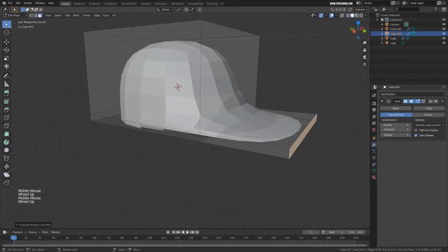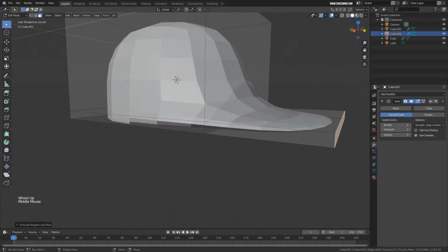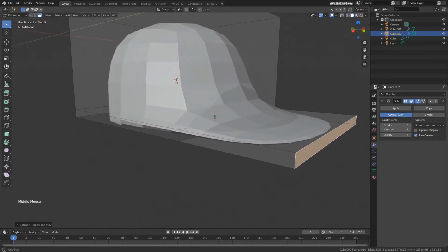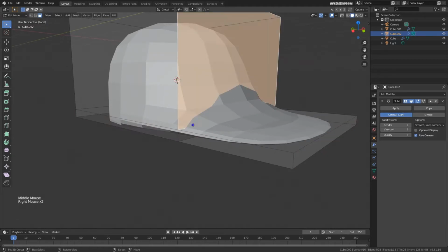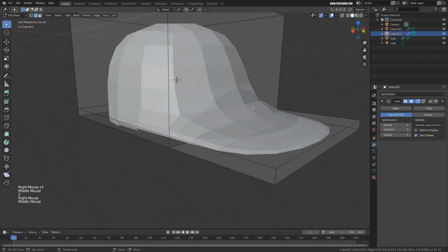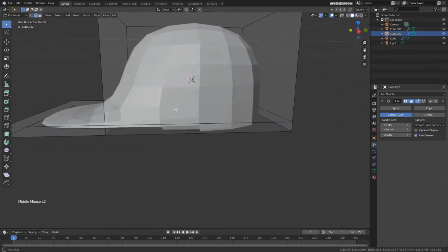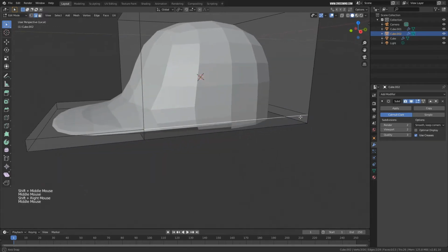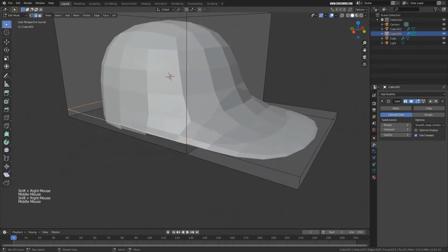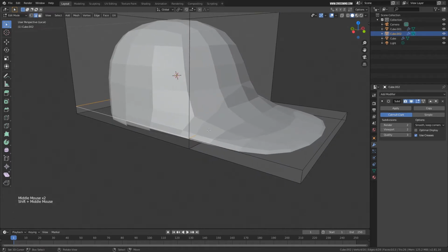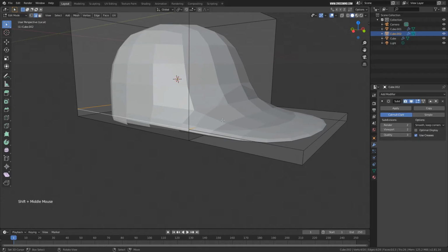Now you can see this area is smoothed out, and I wanted this edge to be much sharper so that I could see a nice shape of the hat. Right now it's getting all mixed up. If I select this entire loop, it's important to select the entire loop because otherwise it will not form the geometry in the polygons if I only bevel this one.